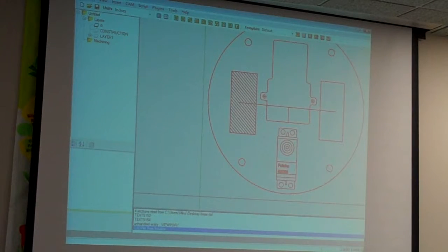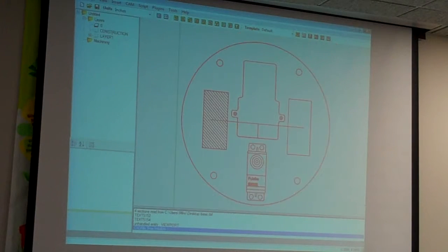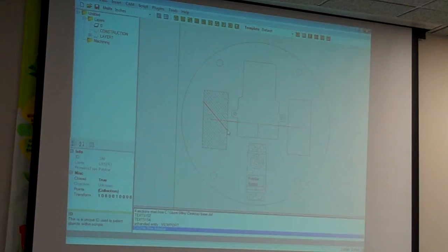So now I can pick what things I want to put into this operation, right? What I should have done in the CAD program was taken all these hash marks out because they're not important to the part. I should have just gone through and made it look like this one. So I would just select that and then do the 2D profile and tell it how many steps to take and cut that out. Okay?